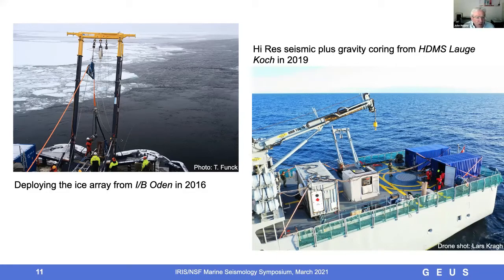The streamer cable then plugs into the umbilical that will eventually support the air gun. So you can see that the streamer is plugged into here, which comes up into here, and the air gun is being suspended from here and will be towed just below this. And then this second shim will go into place here to pay out the rest of the umbilical for the system.